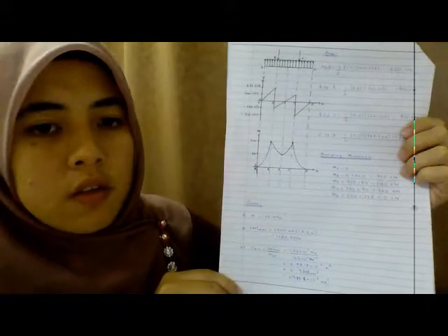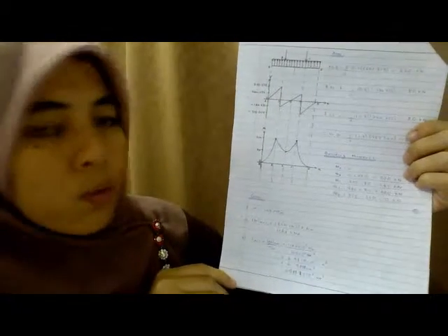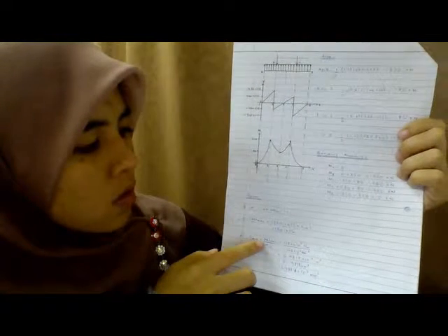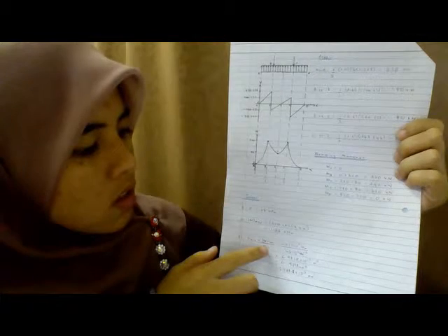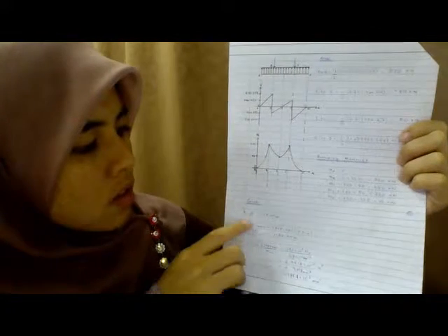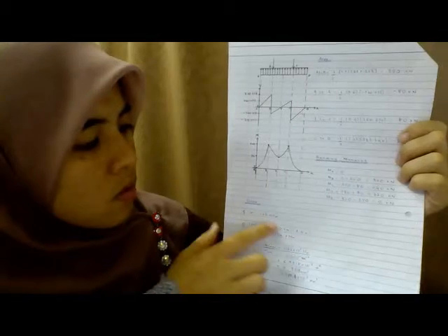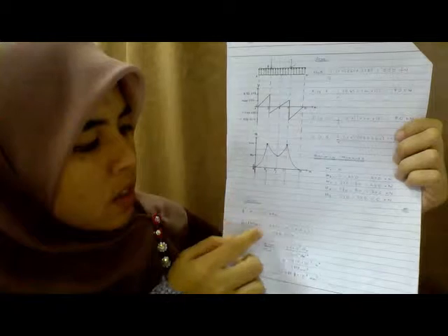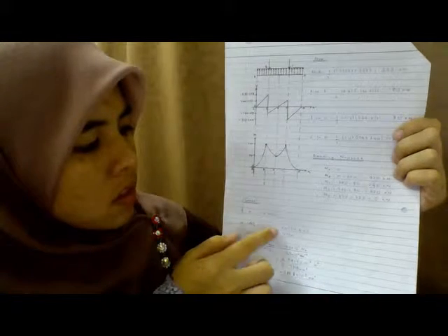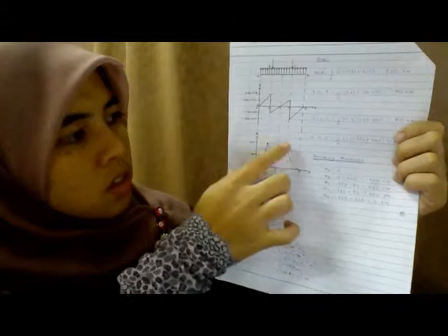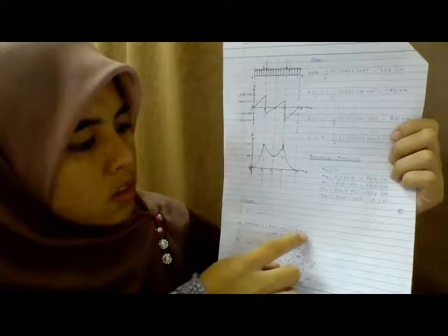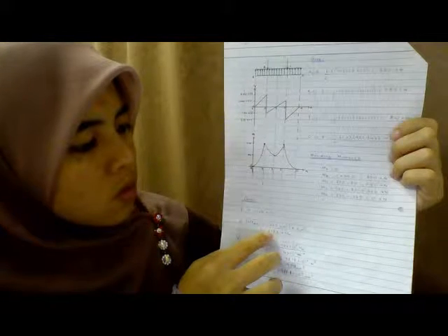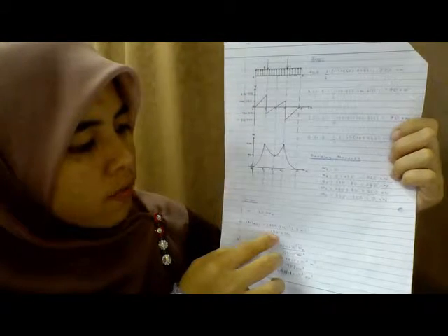And then for the next step, we need to find the most economical wide flange by using this formula, which is S min equal to moment maximum over allowable normal stress. The question has given the value of normal stress, which is 165 MPa, and we have the moment maximum, 320 kilonewton times 3.6 meter, which is the distance between A and D. So we get 1,152 kilonewton meter.